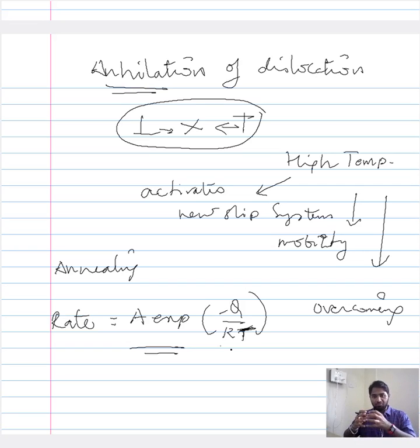Now, by virtue of the temperature that we hold this material at, there is a decrease in the dislocation density. That means the newly forming dislocations can propagate easily, or the existing dislocations which have not been annihilated can propagate easily. Ultimately, that means that because of the temperature you are at, the plastic deformation is now enhanced.